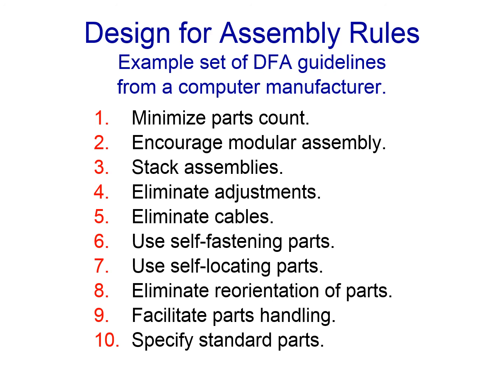While if you do things from the side, or try to plug things from the side, gravity works against you and may misalign the parts that you were trying to insert or assemble, and you may need tooling and fixtures to hold the parts in place while you do more assembly. So in general, if you start from the bottom and then build up and then put the top on, a lot of products are assembled that way. This is called Z-stack assembly.